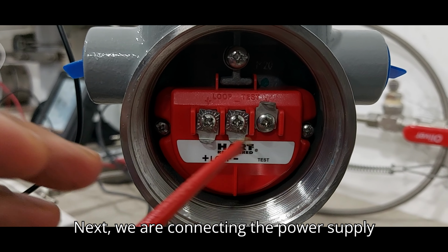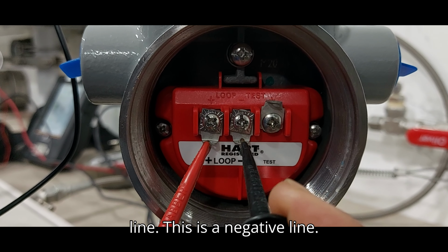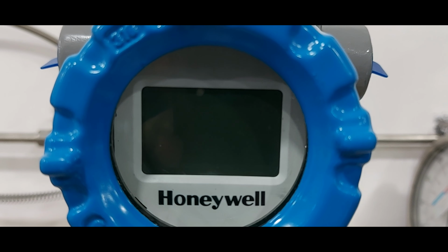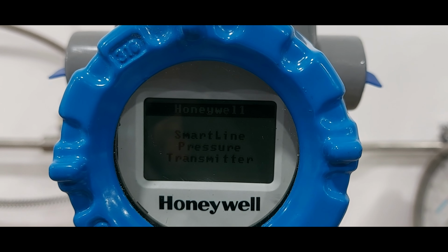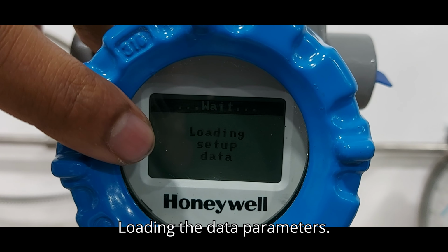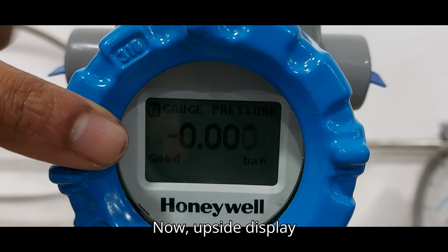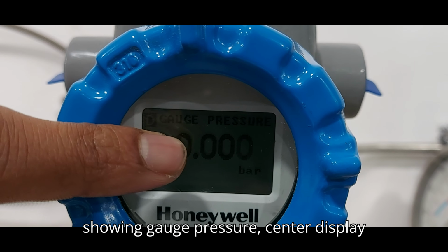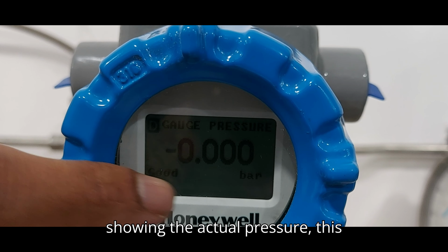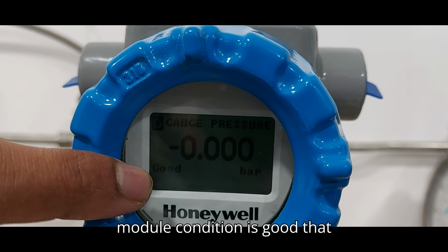Next we are connecting the power supply to the transmitter. This is a positive line, this is a negative line. Now the transmitter is powered on. The display is showing uploading parameters, loading the data parameters. Now the upper display is showing gauge pressure, the center display showing the actual pressure. This is the unit, and the module condition is good.